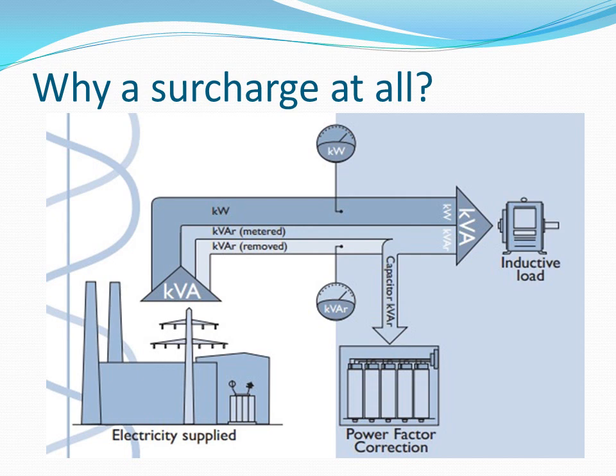This means that if you have a poor power factor, BC Hydro is responsible for correcting it to maintain power quality in the grid. This can be very costly to maintain. As we see in the figure, the total kVA includes not only the real power, but the reactive power that must be supplied. A greater reactive power lowers the real power that can be supplied through the existing infrastructure. This essentially reduces capacity of the system.